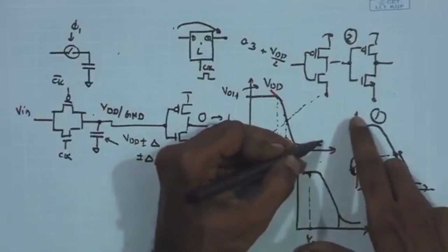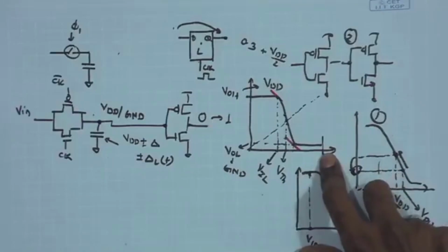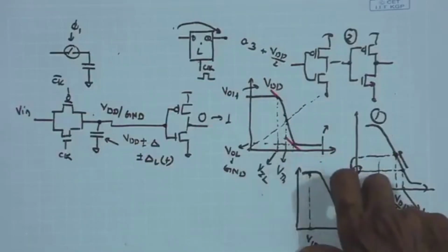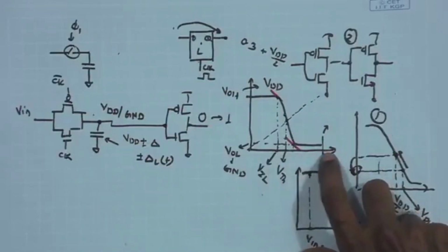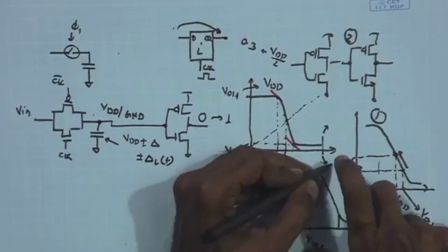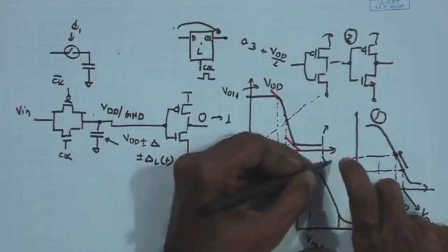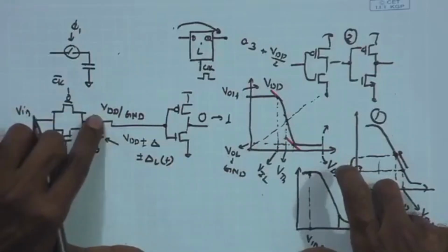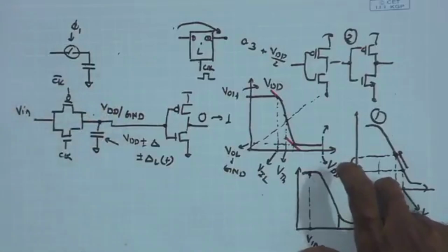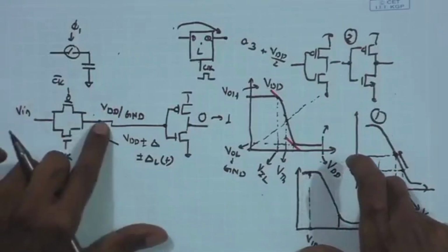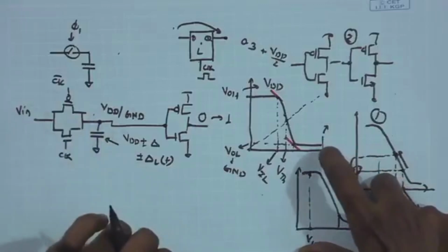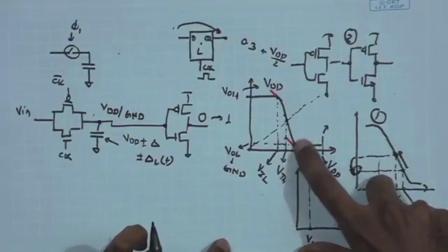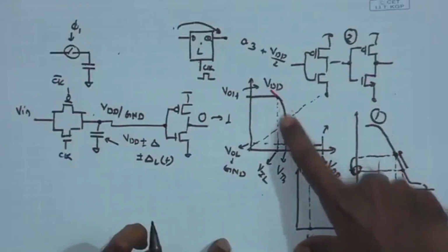Likewise, if the logic high level is supposed to be VDD, it is here on the x axis, the input of the inverter. Initially the logic stored here is expected to be 1, that means this node is charged to VDD, and then once again because of some leakage this voltage is dropping and approaching this particular point, at which once again you are entering the high gain region.